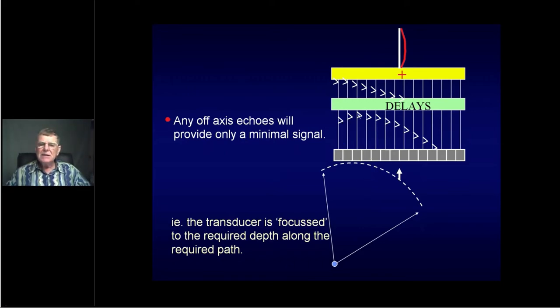The signals coming up from the individual wires will look something like what I'm showing on this diagram. When they go up into the delay circuit, the delay circuit's set for a symmetrical beam coming from the center here, not for this asymmetrical beam. Therefore, the voltages after the delay circuit will not be all nicely lined up. They will be off center like this as well, and they will produce a lower amplitude signal.